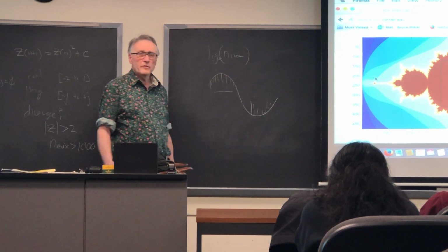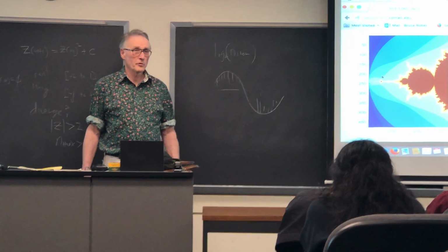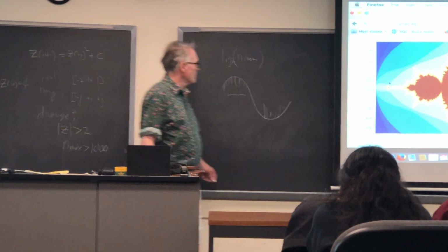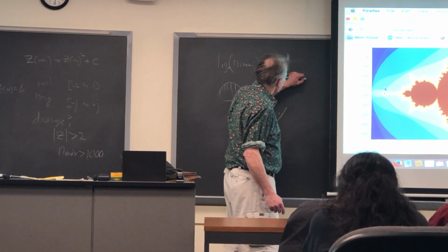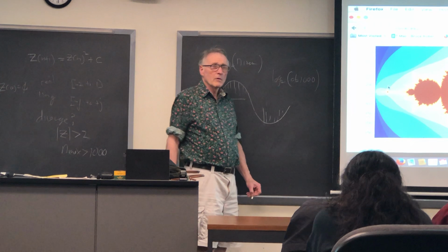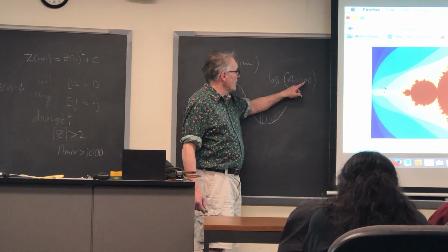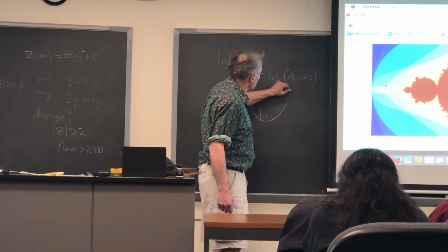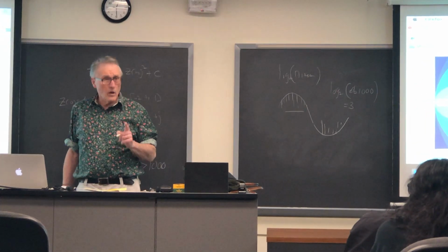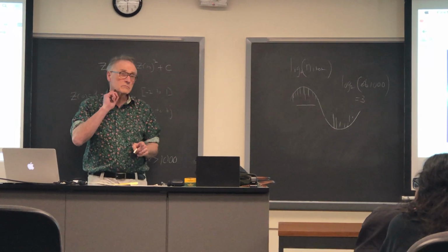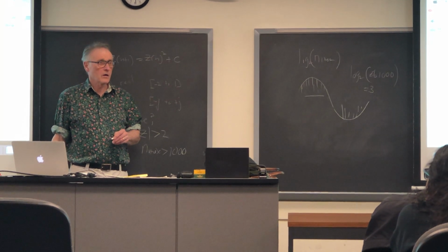How do you take the log base 2 of a number? It's the position of the high order bit. Let's say we have log base 2 of binary 1 0 0 0. What's the log? 0 1 2 3. Oh, it's equal to 3. So the position of the high order bit is a reasonable approximation of the log. So a priority encoder in Verilog takes the log.